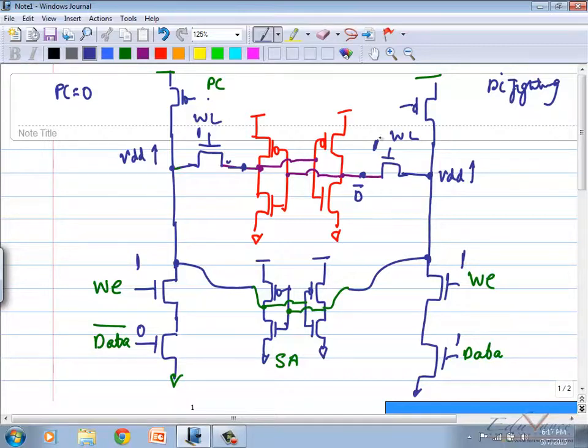This is actually the same wire. This is the same wire. So this is on. This is on. Please observe very carefully. Follow the mouse. This is on. This is off. Similarly, this is on. This is on. Now, do you agree that this node will get pulled down to ground? Yes or no? NMOS passes a strong 0.